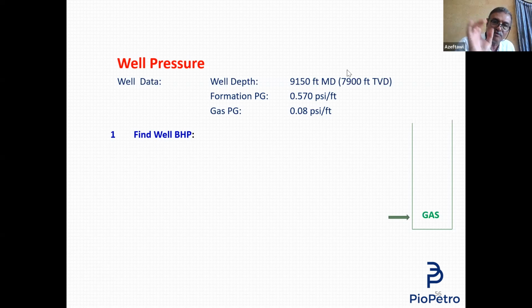So the aim of this, back to my question, the pressure gauge in your hand, and you are sitting now at 10,000 feet, will read what? It will read the highest pressure. If this well is dead, the pressure gauge in your hand will read the hydrostatic head pressure. If the well is alive, the pressure gauge in your hand will read the formation pressure. The pressure gauge reads the highest. It cannot calculate anything. I hope you agree with me on this.